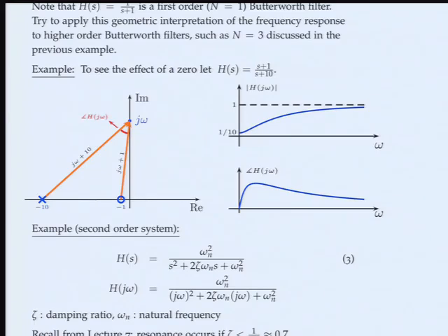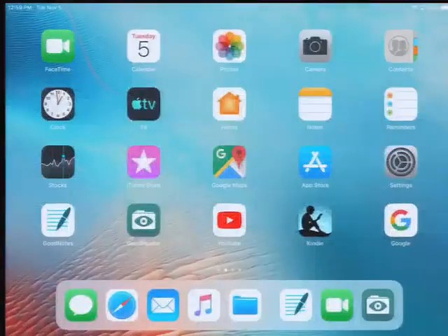So the Bode plot is a lot more accurate than that, even though it has some approximation errors. It also looks prettier. It is like a straight line plot, because here omega was on a linear scale, whereas when we do Bode plots, we use logarithmic scales. It's a log-log scale for the magnitude, because we also look at the log of the magnitude, right? And it's what you would call a semi-log scale when you look at the phase, because you don't mess with the phase. It's still degrees, right? You don't look at the logarithm of degrees or anything like that. But the omega is still in a log scale, right? So that's something you sort of saw in 16. Now you've seen it completely.